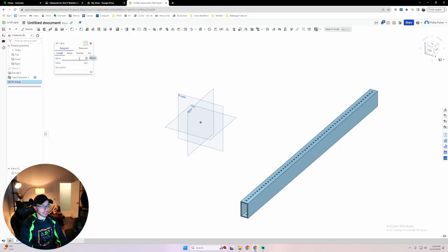I'm going to call it length. And this is a variable that I am going to modify. So I'm going to put caps lock on. It's my standard convention that anything that's off the shelf or standard, like 0.196 for a number 10 bolt, would be lowercase t-e-n.